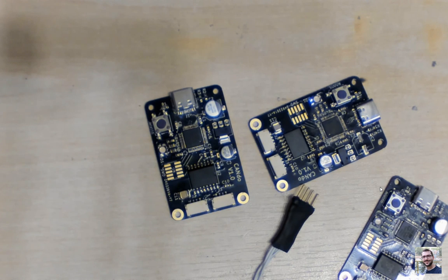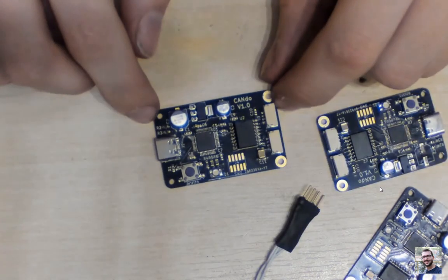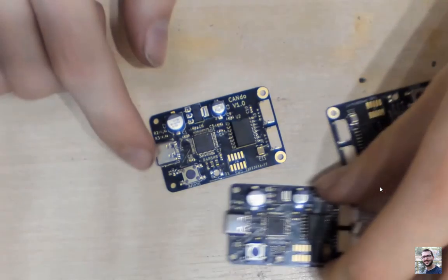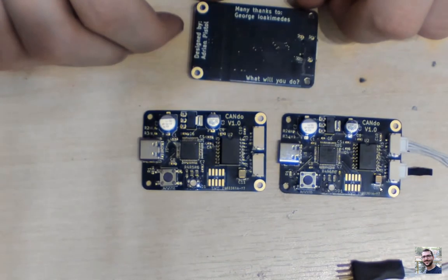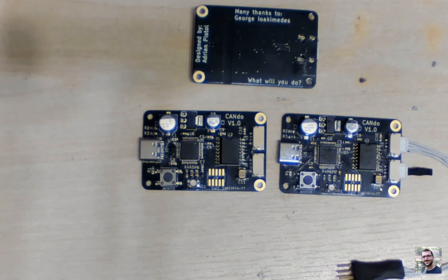Nice. Yeah, I put the video in full screen now so people can see it closer also. Since the boards are on display, let me orient them the right way around. So are those small capacitors 0402 or 0603? That's 0402. Nice. But then you went for quite a big button and the LDO. But I'm guessing since the electrolytic caps are also so big, there's no reason to really save space. Yeah.